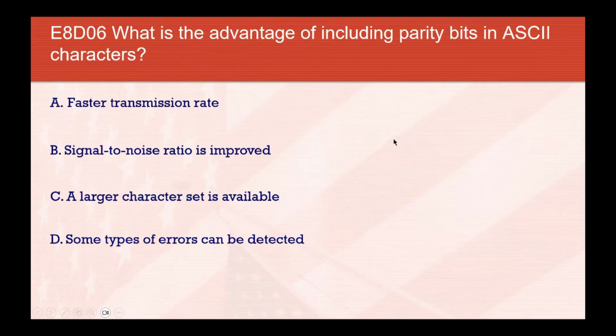Advantage of using parity bits, that's where I was getting ahead of myself. Allows a little bit of error correction. It's not a sophisticated error correcting technology, but it does work just a little bit. Parity, by the way, is where we take that last bit, make it a 1 or 0, and it's predetermined on how we're going to determine that. For example, if it's a 1 bit, it may indicate that there is an odd number of 1 bits in that particular character, or it can be a 0, meaning there is an even number of 1 bits, however it happens to be defined. But anyway, by looking at that parity bit and then counting the number of bits that it describes, we can do an elementary form of error detection.